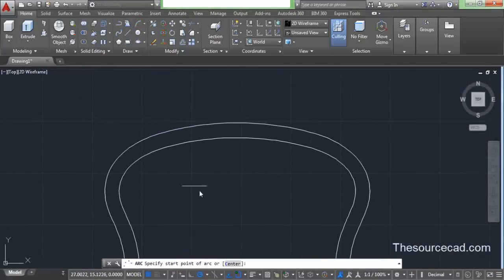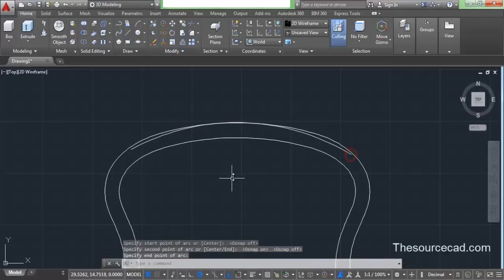So I'll select arc and make an arc. You might need to turn off and on this O snap marker again and again because when it is on it will snap to random points. So to avoid it, you just turn it off. So here we have our arc, 3-point arc, and make sure this arc lies inside this spline. It's completely inside this spline, as you can see.